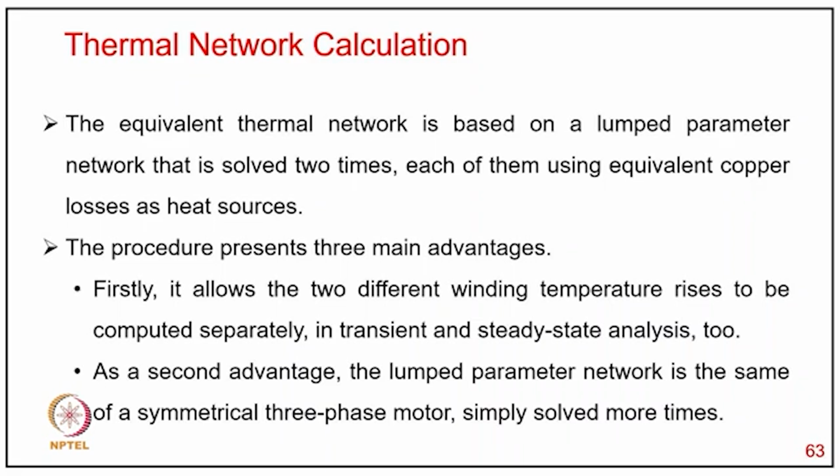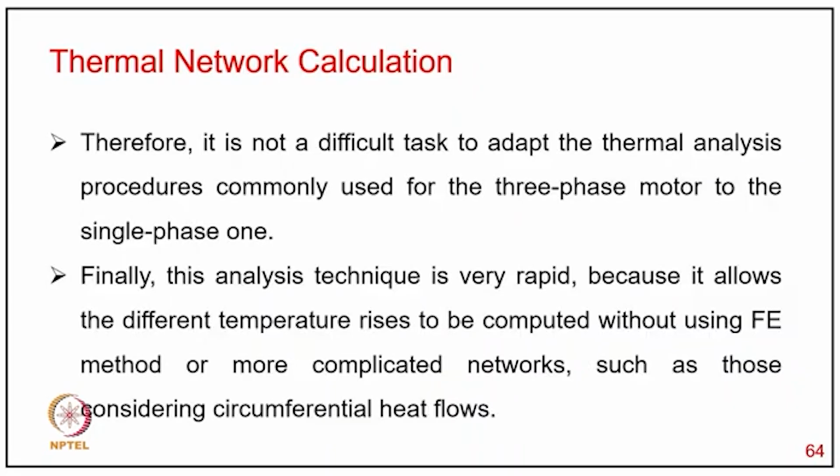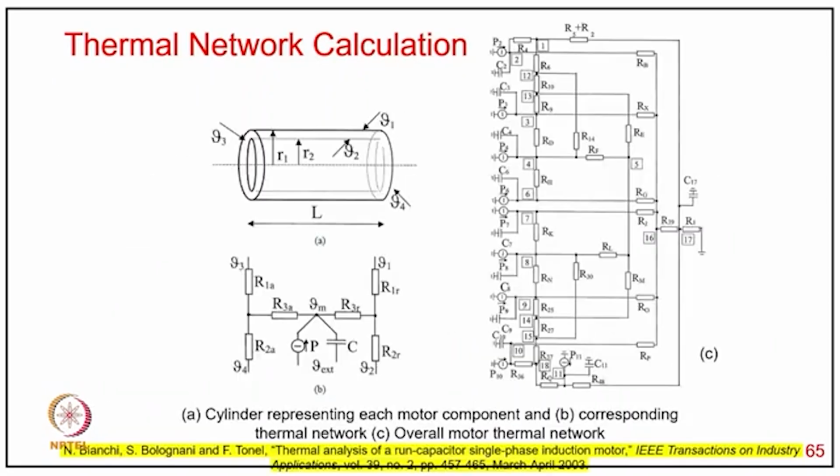As a second advantage, the lumped parameter network is the same as for a symmetrical three-phase motor, simply solved more times. Therefore, it is not a difficult task to adapt the thermal analysis procedures commonly used for three-phase motors to the single-phase one. And finally, this analysis technique is very rapid because it allows the different temperature rises to be computed without using finite element analysis or more complicated networks, such as those considering circumferential heat flows.